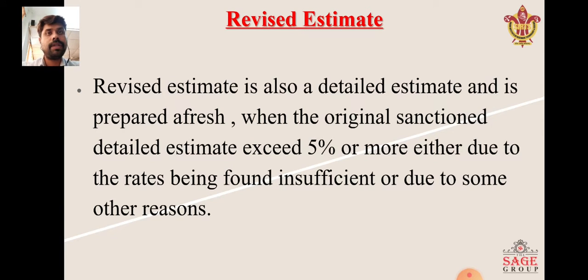Revised estimate. Revised estimate is also a detailed estimate and is prepared afresh when the original sanctioned detailed estimate exceeds 5% or more, either due to the rates being found insufficient or due to some other reasons.